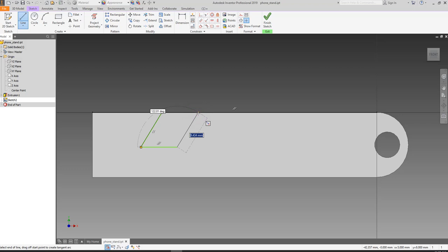That means the 2 angled lines are parallel. It's kind of hard to show you here, because if I move the mouse marker, the constraint symbol would disappear. So if I'm out here, there is no constraint showing that these 2 lines are parallel. And here they are parallel, there they're not parallel. I'm going to set them so they're not parallel, just to show you how to use the parallel constraint tool. So I'm just going to click so I snap onto the upper edge. So just click there.